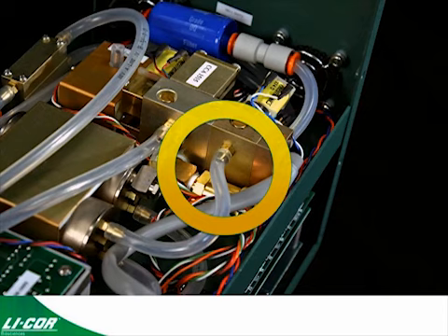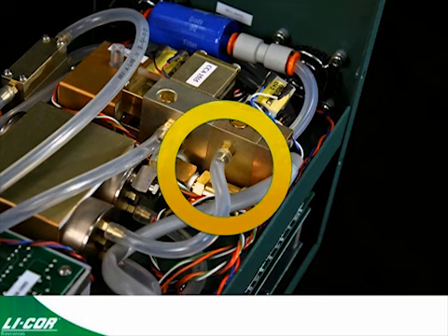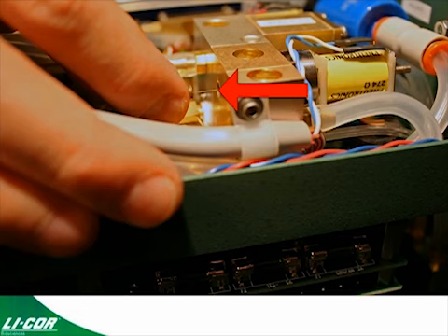Now, just a word of caution. The hose barb on the outlet of the CO2 mixer, as shown here in the circle, has a very fine tube running through it. Be very careful of this rod that is inside that hose barb. The rod is a very fine glass tube that can be sheared off if you remove that hose barb at an angle. You want to remove that hose barb from the CO2 mixer straight to avoid any damage.